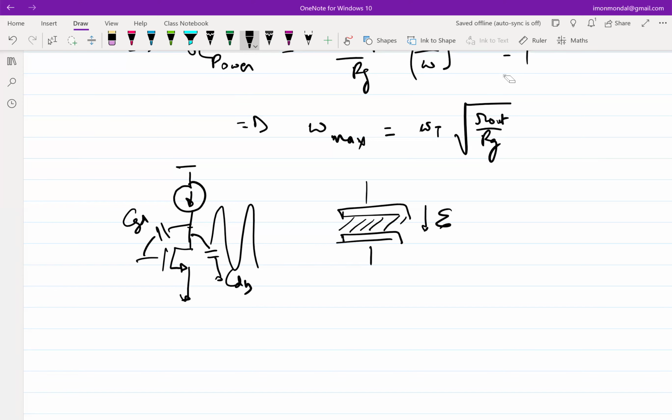Probably not a fair question, but what do you think based on the thickness of the dielectric? Let's say you have two capacitors in which one dielectric is thicker than the other. Will the thinner one have more breakdown voltage or less? Less breakdown voltage, right? So as it turns out, the CGD capacitance has a dielectric thickness of TOX.